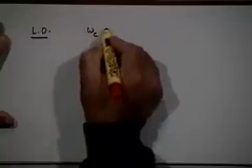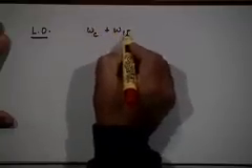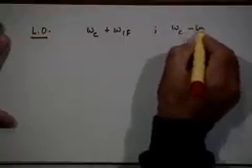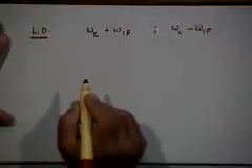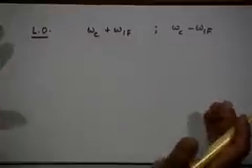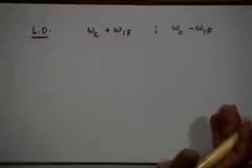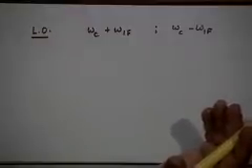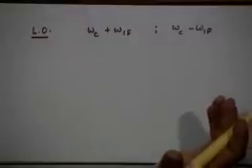One last issue in this connection. Let us look at the local oscillator requirement. We could choose a local oscillator frequency which is omega c plus omega IF, or we could choose a frequency which is omega c minus omega IF. Is there any preference for either of the two? What would you like to say on this? Which one would be better and why?